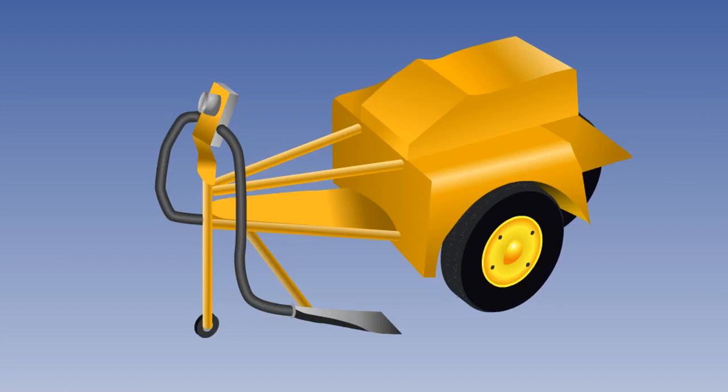The friction coefficient under any set of conditions would be measured by a mu meter or equivalent towed along the runway, usually by an air traffic control vehicle. The device is towed at a given speed, typically 40 miles per hour. It has 3 wheels, the rear central one measuring speed and distance, and the front 2 which are angled slightly inwards or towed in, sensing the friction between the tyre and the runway surface.